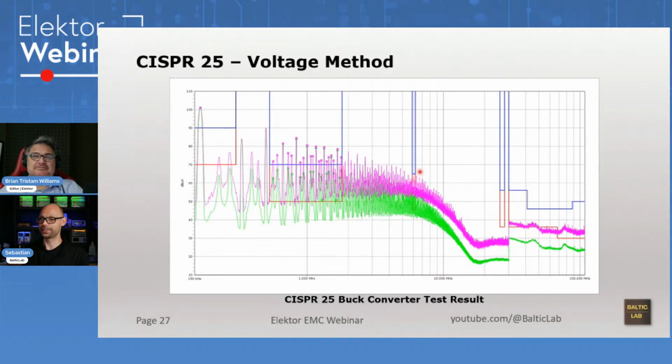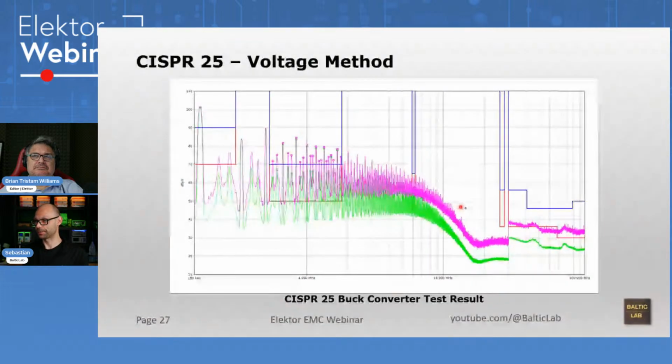Electromagnetic compatibility is the enemy of efficiency. If we switch extremely fast, we get rid of switching losses or minimize them, but our spectrum will stay higher for much longer, and that is a problem. And since we see that here, I just thought I'd point that out.